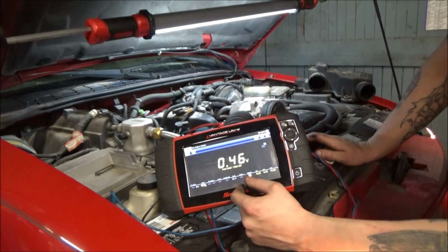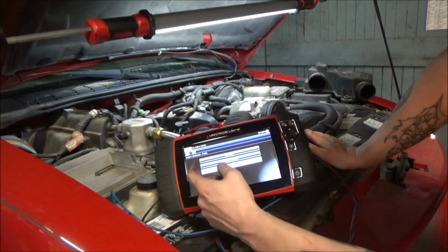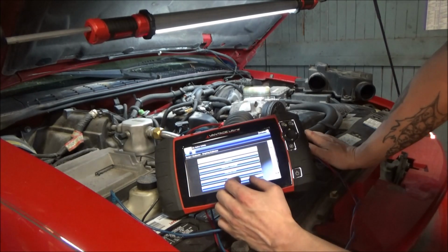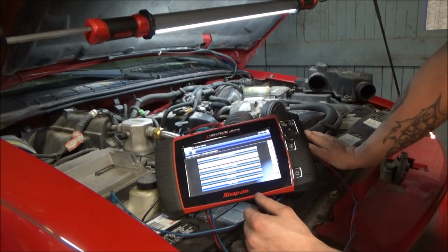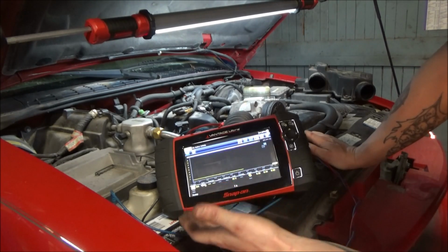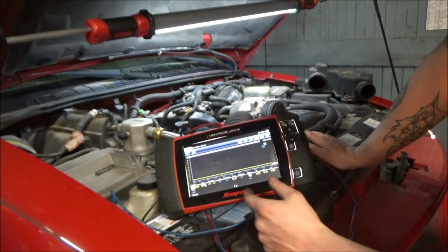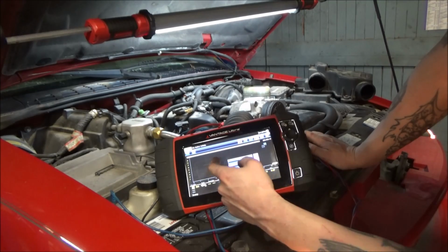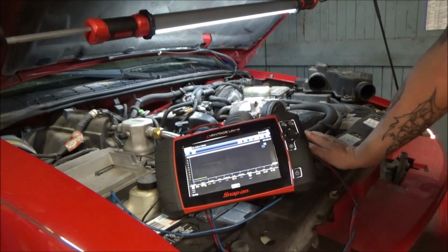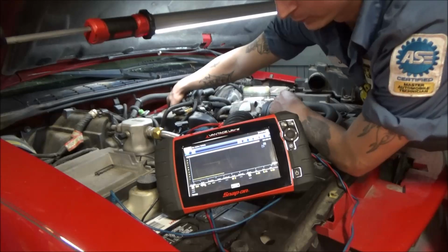What I want to do for you guys to better emphasize these dropouts is let's go to our graphing meter and actually graph this signal over time. I think that's really going to emphasize what this glitch looks like to you guys. Doing it on the digital multimeter isn't really the clearest way to go about it. So I'm just going to widen this scale up a little bit. We'll go to a 10-second scale, should be sufficient. So I'm just going to slowly open this, guys, and we're going to watch the Vantage.